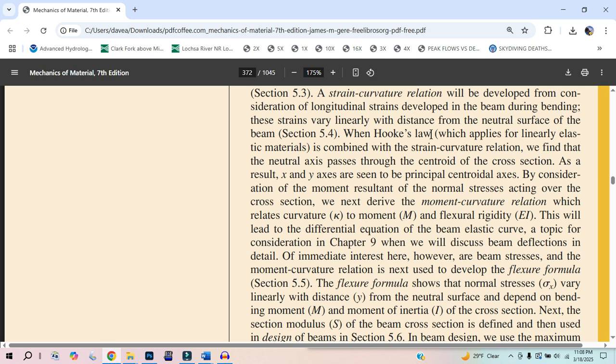Double that pressure, and then you just change this length by double. So that is the fundamental aspect of material mechanics. It's the idea that everything's a spring. And you can keep things in what we call Hooke's law, which applies for linearly elastic materials.